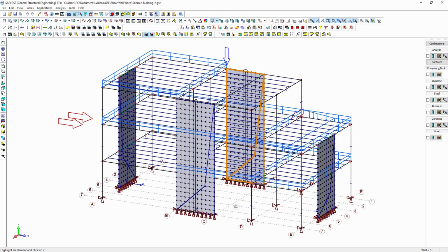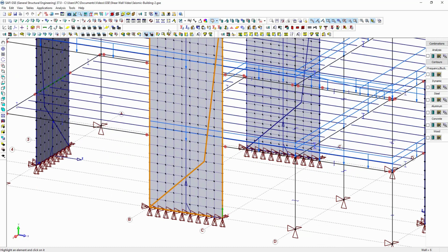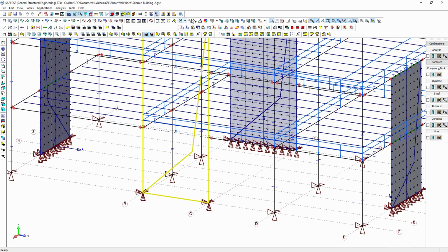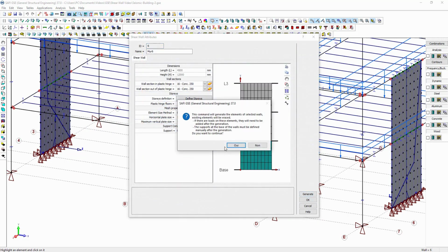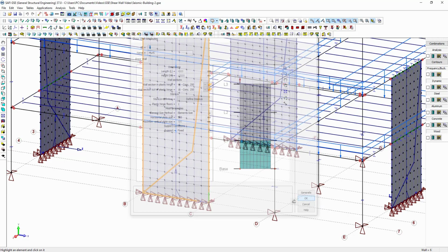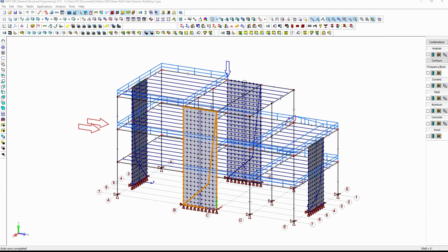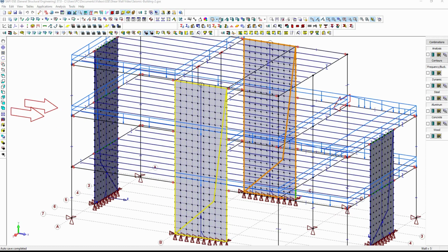So, just to show how easy it is, I'll just go in and remove the different plates from this wall. I will clear this wall. And if we go back in the interface, we can simply go here in the edit and use the generate button. So as easy as that, you can quickly generate the concrete shear wall within a model. Once the shear wall is generated like this one, we can then go and select the integration line directly in this model. This will provide all the results for the analysis within the model.